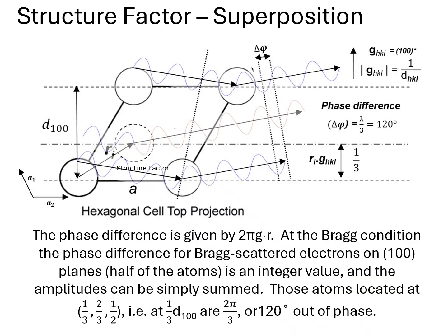It gets a little bit more complicated when you look at the hexagonal structure because the atoms are not exactly halfway up between different planes. If we're talking about setting up the diffraction conditions for these planes, the prism planes, for instance, and this is the unit cell, and we look at scattering from the atom within it, the intermediate plane has the same atomic density.